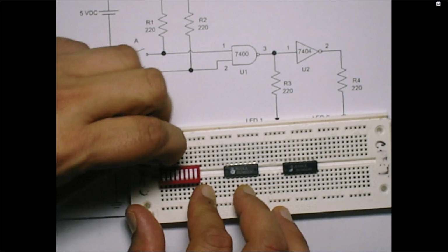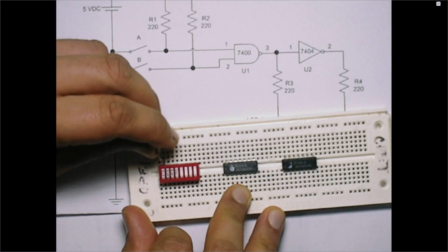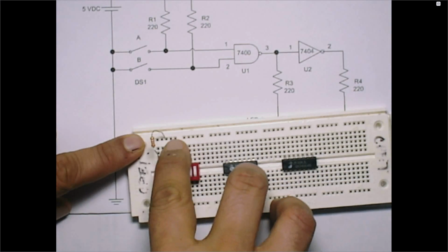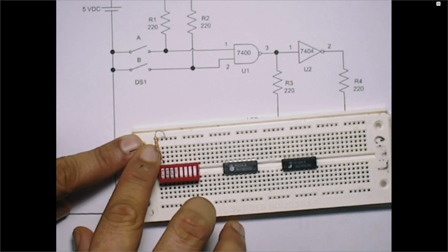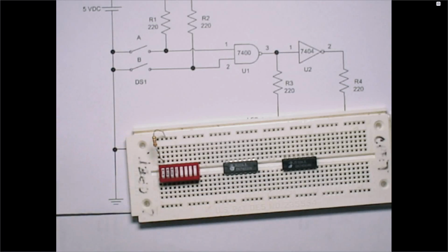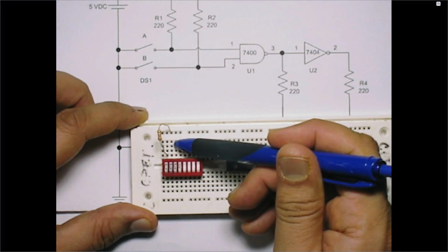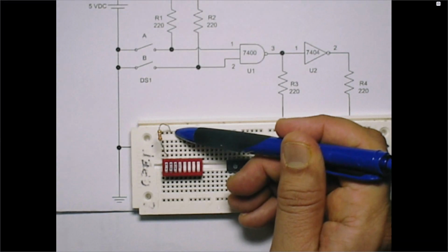So I'm now plugging my resistor from the switch 1 column to any point on this row. Remember, you can choose any of these, it doesn't matter where you connect. Now when I plug here, see, this is my column, right? I could have chosen any point of this column, so don't assume that it has to be this point. On this column I have 5 points, and I could have connected this resistor to any point, because all those points are the same point. Those are shorted.